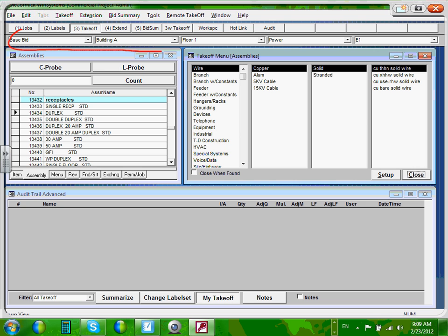Can you guys see the label here that we just designed? This is step number 1. You have to set the label. You have to put the label right. For example, if I'm doing power, can I put power, guys? If I'm doing receptacle, can I take receptacle under lighting? Yeah, it will be full though. You're going to take receptacles and mechanical equipment under what? Power. When you have fixtures and you're taking fixtures, you're going to take them under what? Lighting.